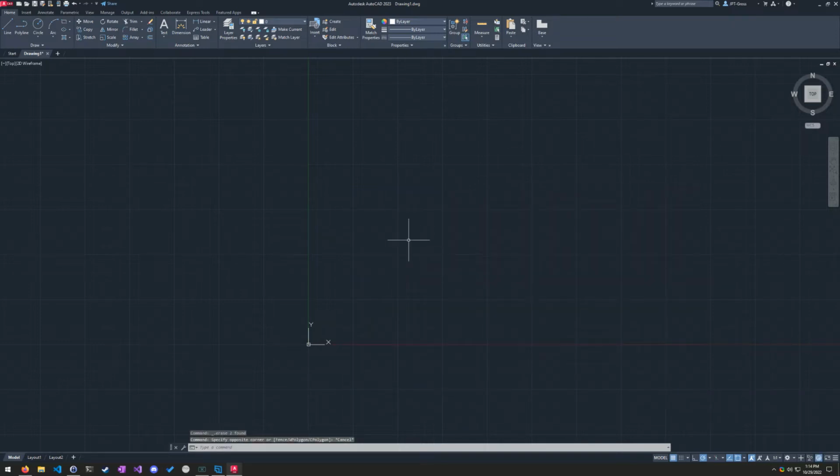But the border that we drew on that paper was not 8.5 by 11, right? We went 3/4 of an inch in on each side. So we're going to do that on our paper here by starting our rectangle 3/4 of an inch in on X and up on Y. So how are we going to do that? Well, first you need to know how to draw a rectangle. And we're going to do that by typing REC. So notice how by my cursor, as I type, you see I'm typing into this little bar by my cursor.